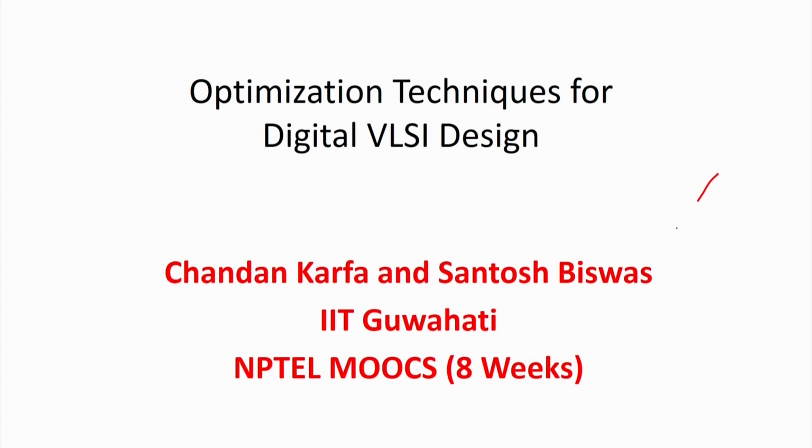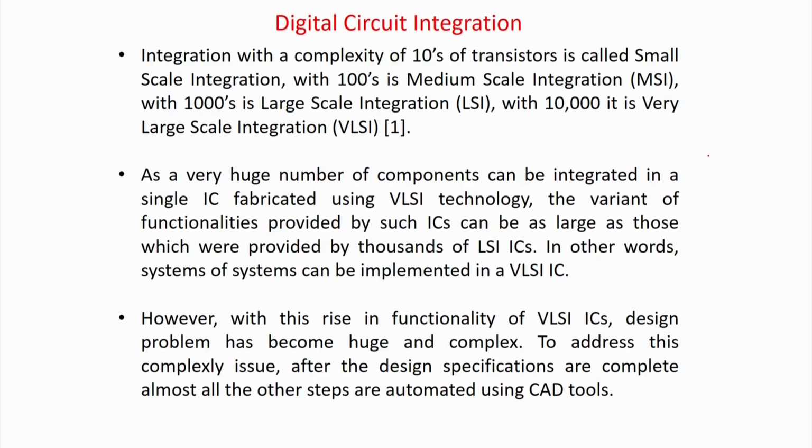There are three basic things you have to optimize. First, I should be able to process the input at an extremely fast rate. So I want megahertz, gigahertz, or even extremely high frequency, so that you can process the data in just a click. Second, we want very low area overhead. Why? Because the more area overhead you have, the larger your circuit will be and the more cost. So you want a circuit with very little area overhead to serve the same purpose. At the same time, nowadays we are talking about power. So basically you have a three-corner optimization problem: area, power and speed.